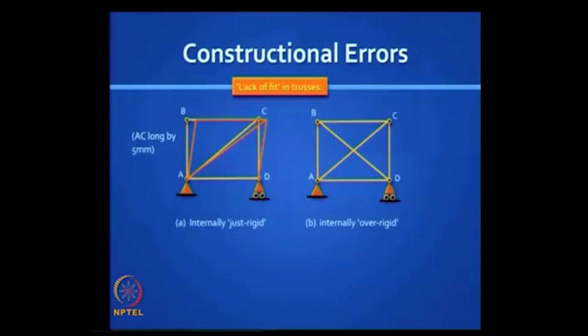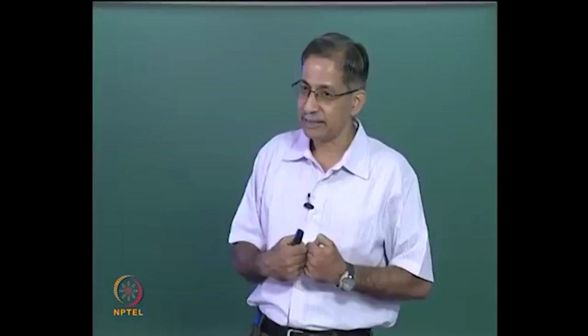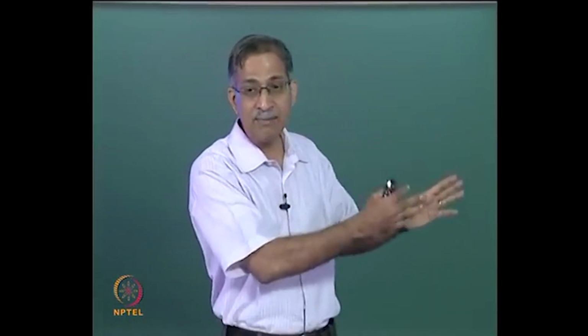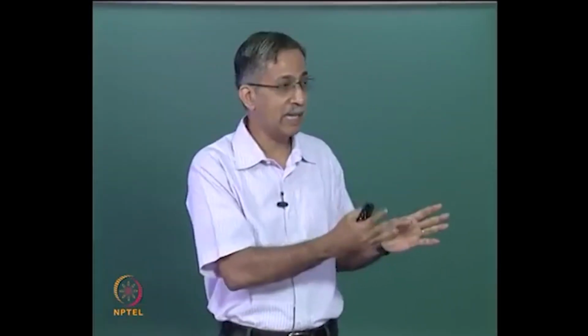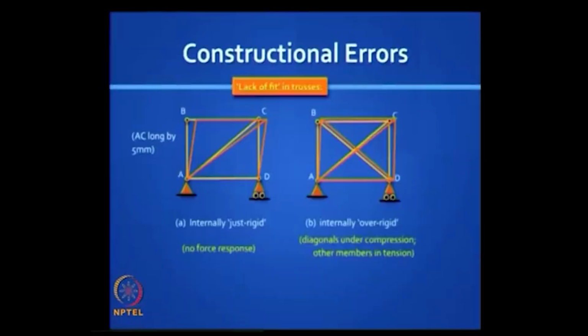But if you try to do the same thing in an over rigid structure, you will have problems because some bars will have to be necessarily stretched and some will have to be contracted. So you have an internal force field created which is self equilibrating. So that is an important point to note.